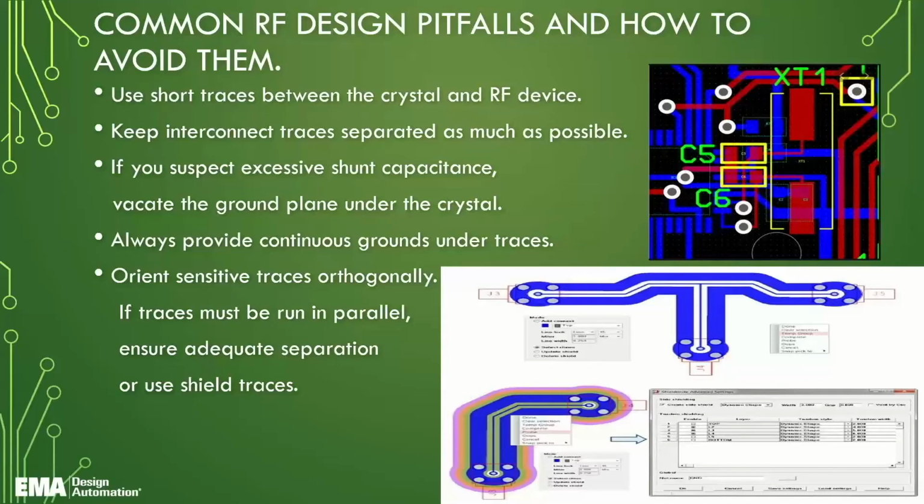I can take that circuit and relay that out, and you will never have a problem with that crystal on there. The other thing that you'll notice is we're not seeing a ground plane underneath that crystal, and we're seeing other circuitry. Underneath there, of course, the crystal's on the bottom, but underneath that, looking at the top, they're routing regular signals through there. I would not do that. I would avoid putting any of those traces in there. You're asking for trouble on those signals by doing this.